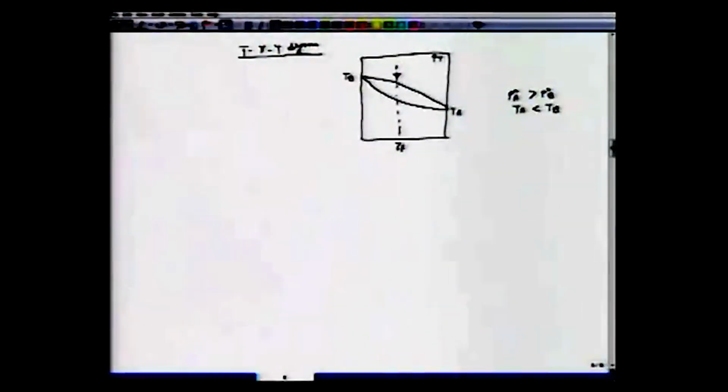All right. So when you start cooling it, what will happen? The first bubble, the first dew will occur right here. Okay, and if so, we call it the dew point curve, which is nothing but the locus of all such dews here. If we start with different compositions, the first dew will appear here. If we start with different compositions, the first dew will appear right here. So we have this locus which we call the dew point curve.